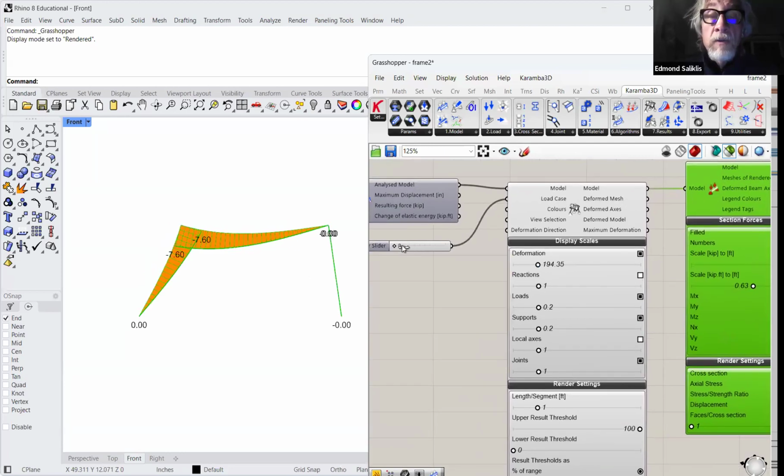And we can get the magnitude of the bending, which I think is in kip feet, according to Clemens here. But let's look at the other load case now, and we have something different, right? We have the lateral load going sideways, and notice I put it at the center of the diaphragm. You could put it at the joint of the beam column interface, but I like putting it at the center of that beam, which I'm calling diaphragm in 3D, correct? But here we do have bending now because the horizontal reaction at the left pin has to equilibrate that lateral load, but it is pinned down there, so we start at 0, and we move up to 7.6, and then we match 7.6 on the beam interface or the diaphragm interface.